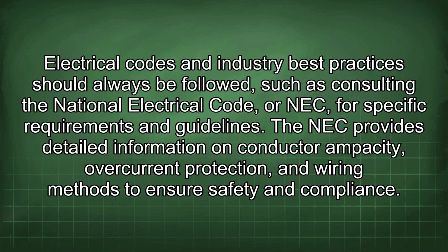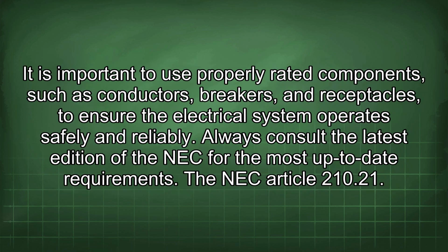The NEC provides detailed information on conductor ampacity, overcurrent protection, and wiring methods to ensure safety and compliance. It is important to use properly rated components, such as conductors, breakers, and receptacles, to ensure the electrical system operates safely and reliably. Always consult the latest edition of the NEC for the most up-to-date requirements.